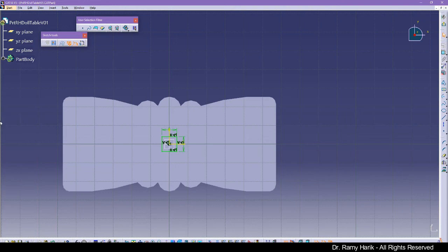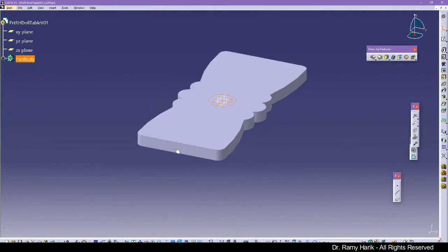And the next thing we have is this diameter of 15 circle. So we're going to select that, do this, come to the center, and I'm clicking on tab. So if diameter is of 15, the radius is of 7.5. All right, so like you see how we are creating very quickly iso constraint sketch.